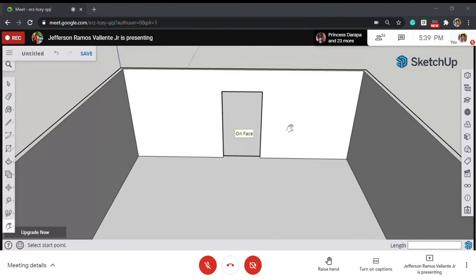So sa window, again, let's use a symmetrical orientation. So from this marker, from the midpoint, I'll draw up at 0.9 meters and then draw the dimension of this window. I'll use 0.6 here and also 1.2 towards the other side. So meaning 0.6 plus 0.6 is 1.2.